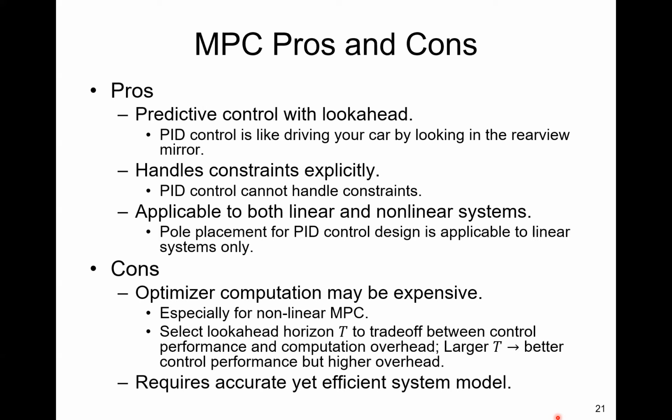As we will see in our project, you can apply PID control. If you have a model of the system, then you can apply pole placement and other methods for controller design, and you can have rigorous guarantees. But if you don't, you can just apply PID and tune the PID gains heuristically, and oftentimes it works pretty well.